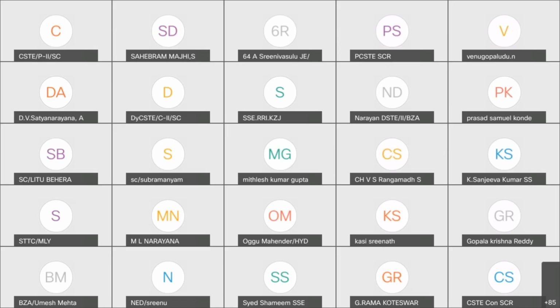First, one group of points is operated. For example, A end of all the crossovers will be operated at one point of time. Then the B ends of the same crossovers will be operated at the second point of time. This will reduce the point power supply requirements.